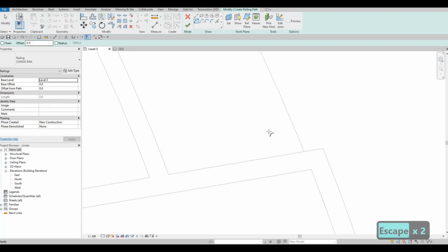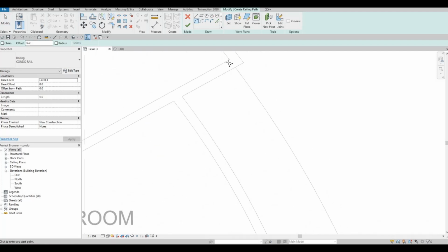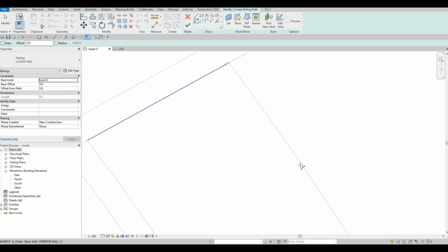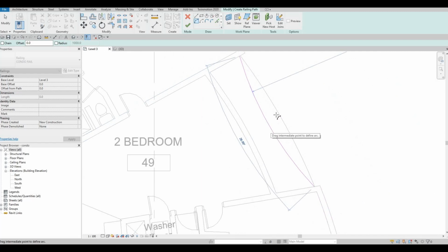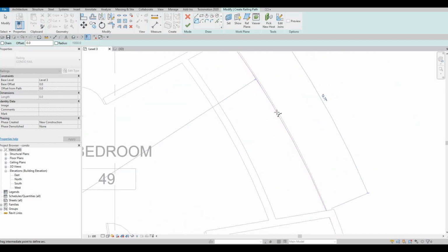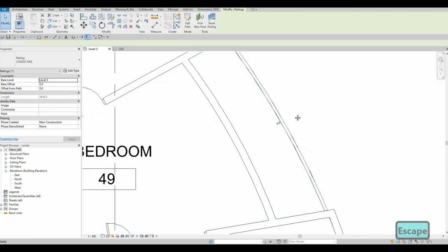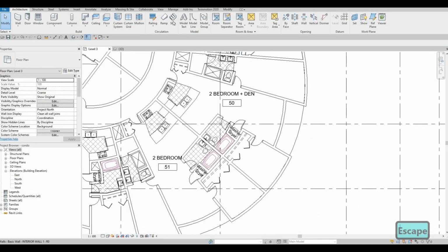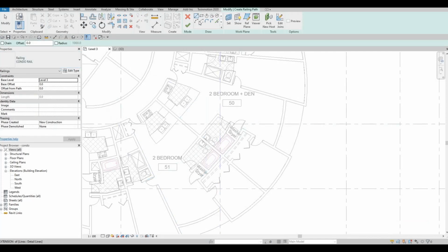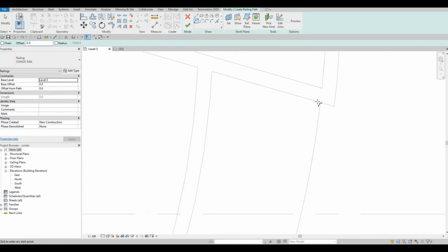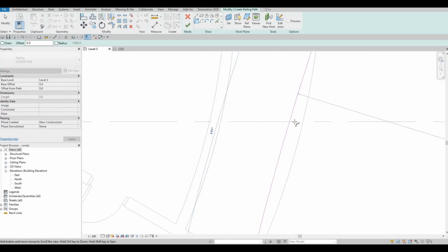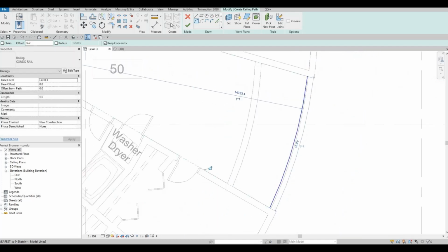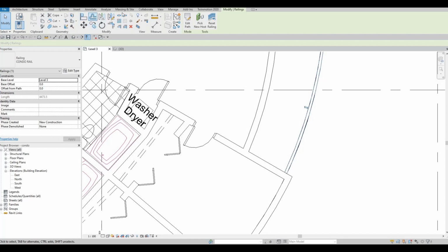So now I'm gonna remove the offset so that I could put it to the position that I want, just a little bit from there, and then zoom out so that you could see the angle. Click finish after, and then here as well. Don't put any offset anymore, and then make sure to use this. Perfect. And then railing again.